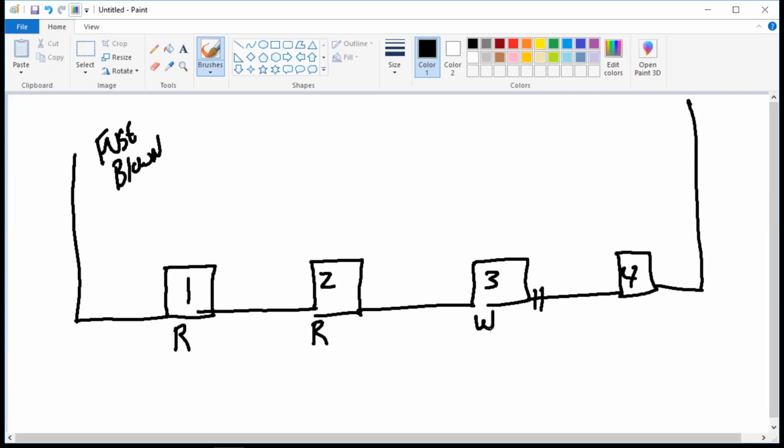B to A, right? Right. From the B side of here to the A side of here. Somewhere in that span, I've got a fault. I am not locating the fault location. I'm locating the faulted span. Okay? That's the fault indicator method.